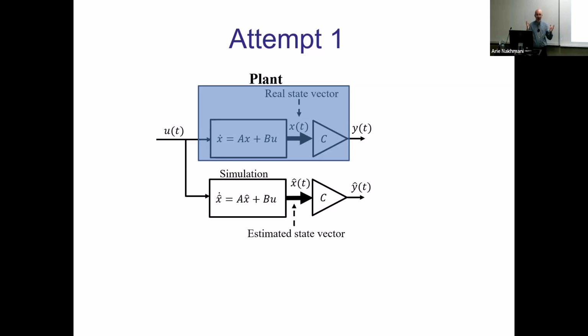So let's say we have the model. We have matrices A, B, C, D, all of it is known. We know how the system works. We know physics. We know whatever sits in the black box. We developed matrices A, B, C, D. So we have practically a linear state space representation. So our observer could be just some algorithm in the computer which is simulating the system and computing X from the same kind of system.